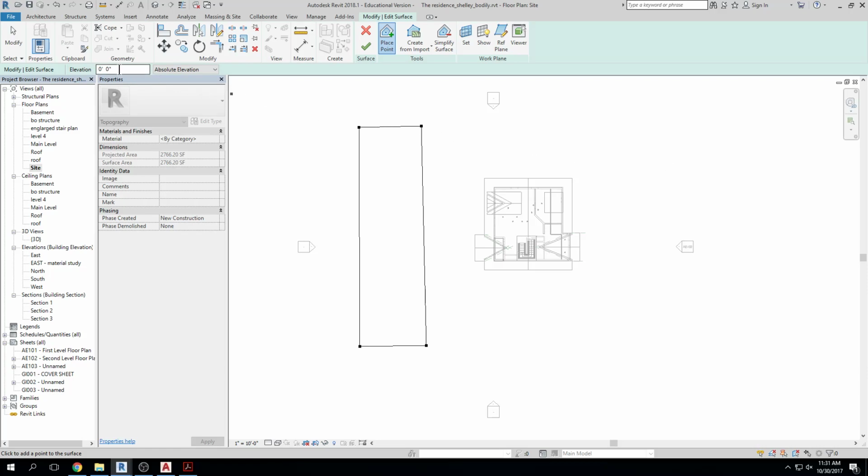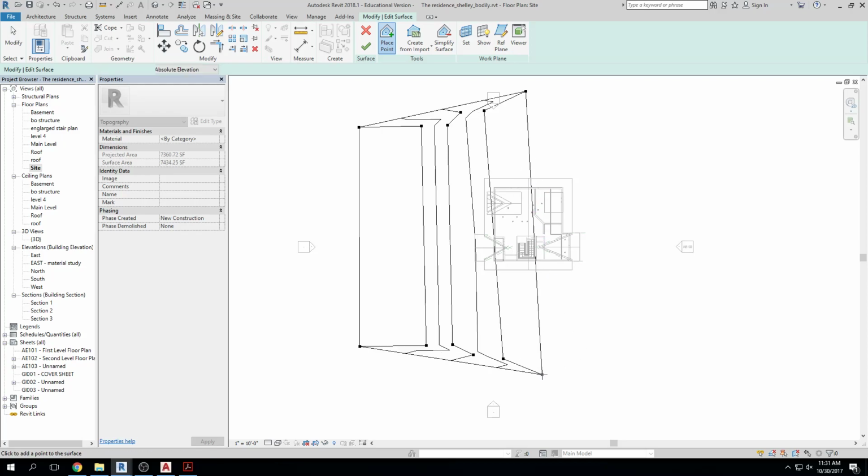So I'm going to increase the elevation of my next point to 2 foot. Enter. Now when I click, click, click, you see I start getting some contour lines, indicating I have slope. So it's 0, 0, 0, and it goes from 0 elevation to 2. If I keep clicking, like out here and out there, I get more slope. Now I'm going to go to 4 foot. Click, click. I can do even more. It goes from flat, flat, flat, then 2 foot increments, and then I go to 4 foot increments.